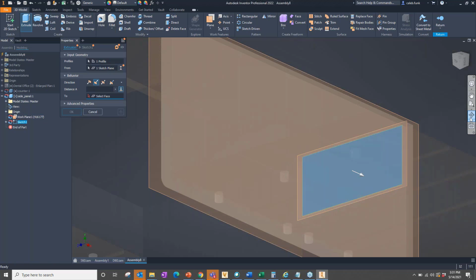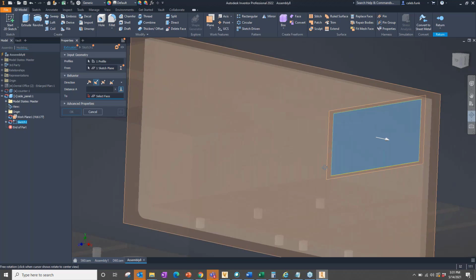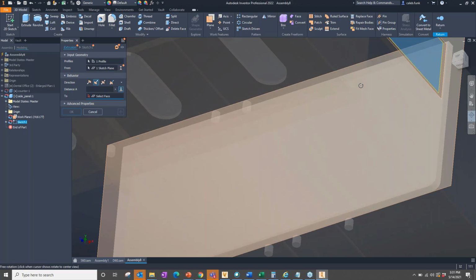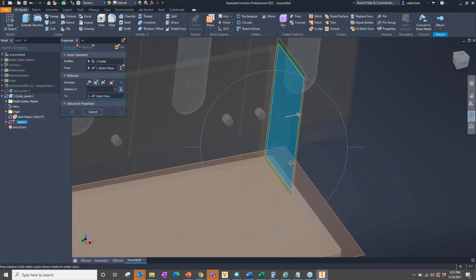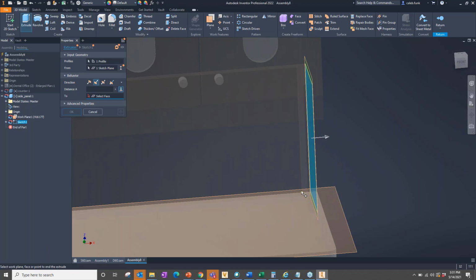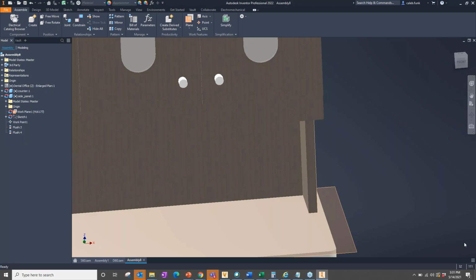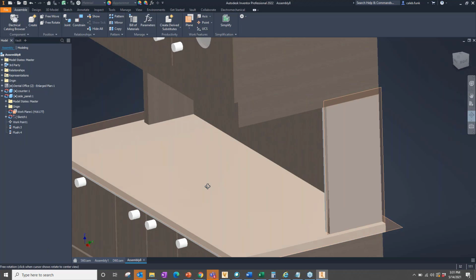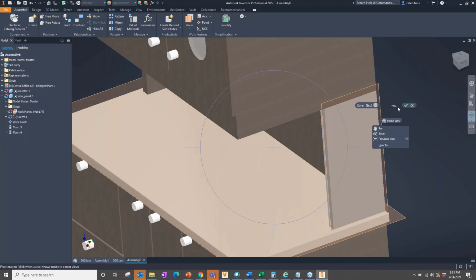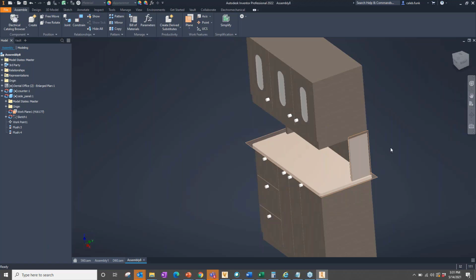And then once I've got it, I'll be able to begin extracting those parts as manufacturable components. Because at this point, they're going to have the Inventor information. They're going to have all of the things that I typically need for that to work. I'll just take it right over there. There's my first side panel. So now, instead of just having this Revit information here, I'm beginning to overlay my components on top. And of course, I wouldn't finish here. I'm going to have to come in. I've got hinges. I've got all of this different information that I would want to put into place. But for a skeleton, I can begin right off of that and steal it from there.